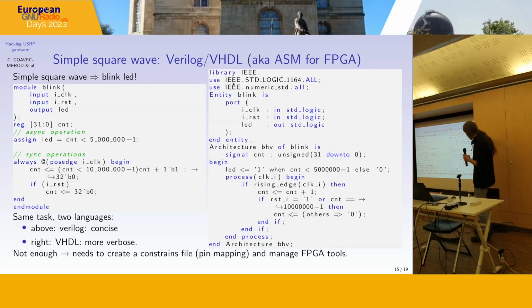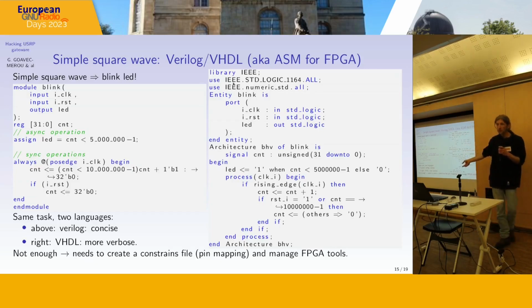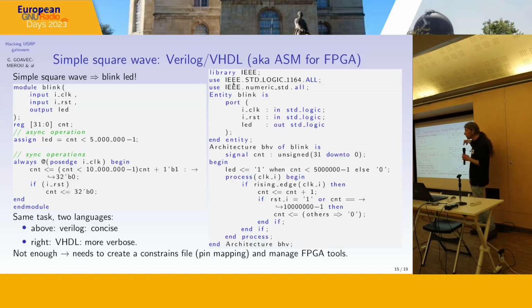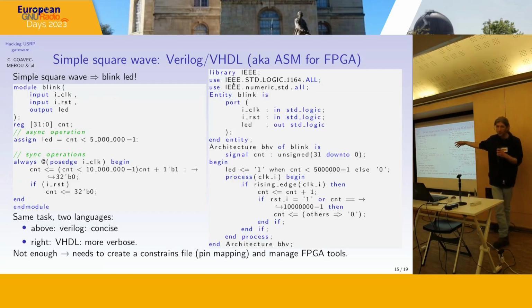And the right is exactly the same thing using the VHDL language. So the first thing you see is it's big compared to the Verilog, and in fact it's really more explicit. The inputs and outputs are typed. STD logic is a 1-bit signal. For the counter and all signals, in Verilog the declaration of a signal may be done anywhere in a file, but before using it.